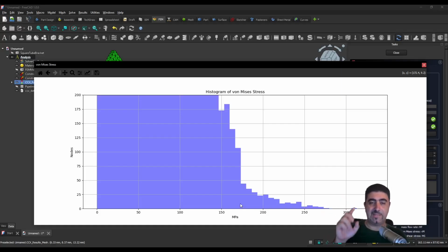So few technical data sheets show a fatigue curve, that as steel fatigues, its strength falls roughly to half. So if I wanted this to last for a lifetime, I need to change it, use a thicker tube, and make sure that these real stress nodes do not show stresses over 100 megapascal.